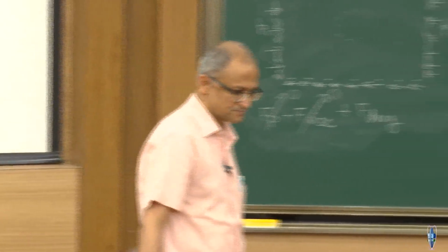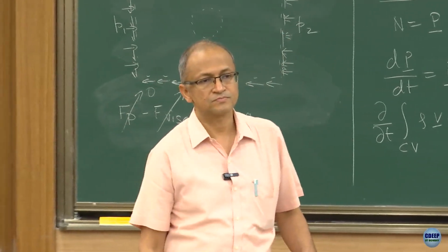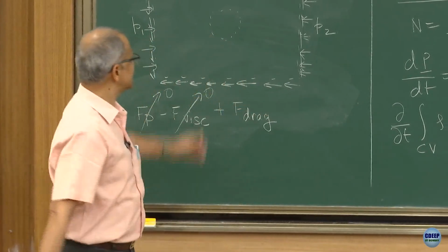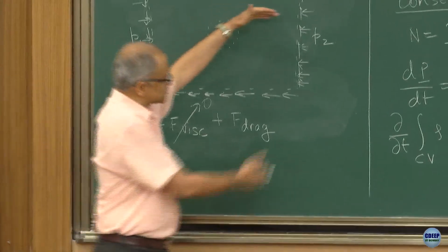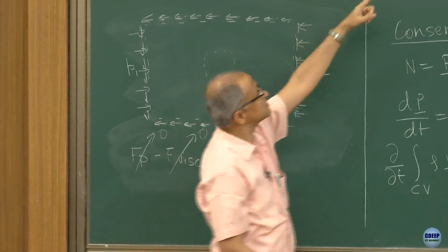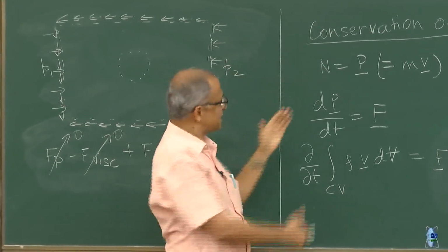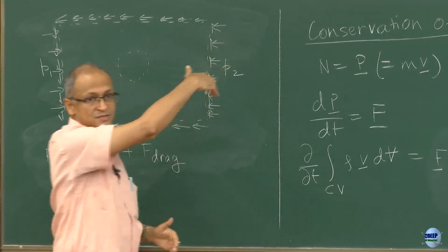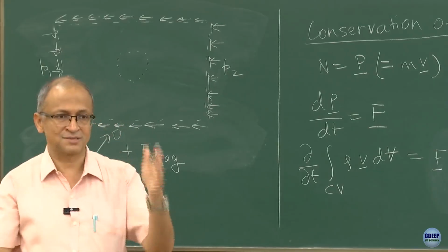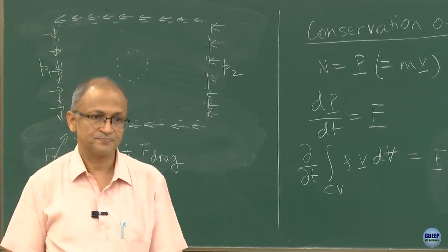Yes. So if you're moving the upper and bottom boundary very far away, that won't affect the mass. The mass will still be exiting over there with some momentum. Yes, the mass will still be exiting, and why is that? Because there is always a velocity deficit region that has been created. As we said, if you look at the integral, for any value of h that you take, my average velocity on the downstream side of the cylinder is less than the average velocity on the upstream side. There will be a mass imbalance, and the remaining mass therefore has to always go out from the sides.